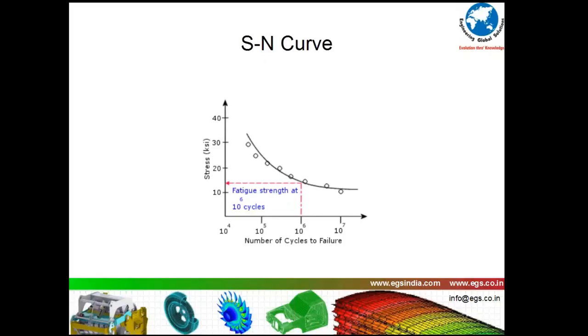One of the questions that people ask is, we don't have the SN curve available. There are enough methodologies available for fatigue life estimation or fatigue curve estimation based on the hardness, based on so many other factors that you can bring in and construct the SN curve even based on the failures that you have reported from the marketplace, including the material properties such as the ultimate tensile strength and the yield strength. You can come up with the endurance limit calculations.